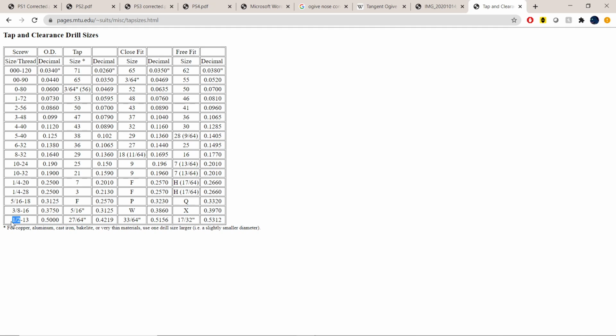So if you go like a 1/2 inch bolt, 3/4 inch bolt, the smaller you get. If you get lower than quarter, it's actually a number standard. So it's 10, 8, 9, blah blah blah, down to like quintuple 0, which is very very tiny. Anyway, we use like 10 and 6 and sometimes 4.